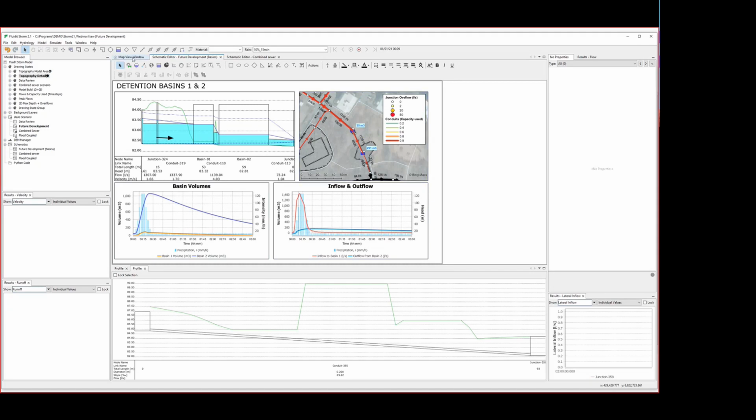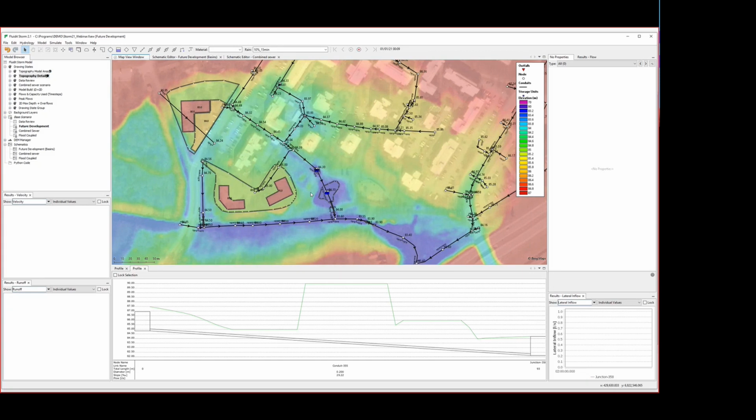One little snappy thing I want to show you briefly is that you can also calculate basin volume or the elevation area curve automatically. So you could, for example, come here and just calculate basin, and you would just lasso over the high points like this.